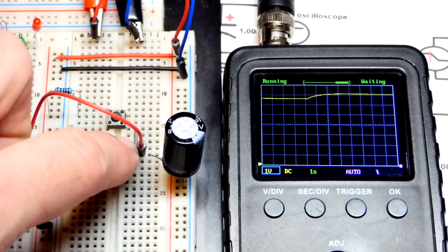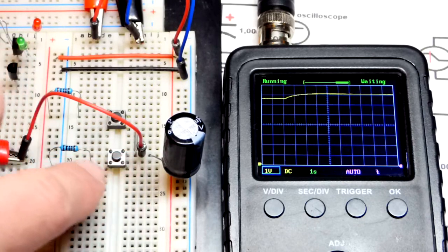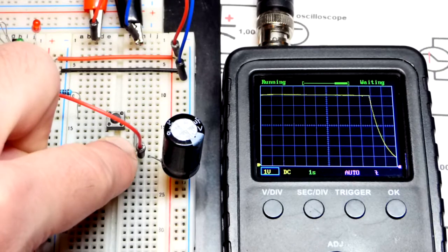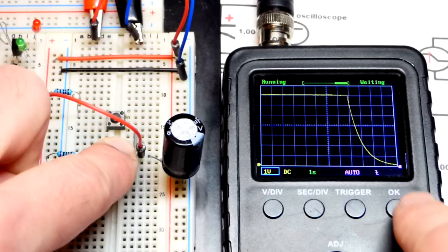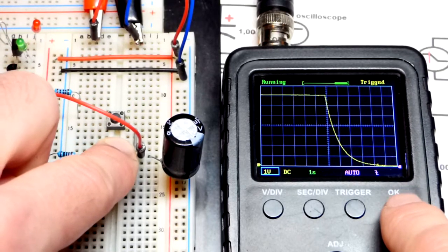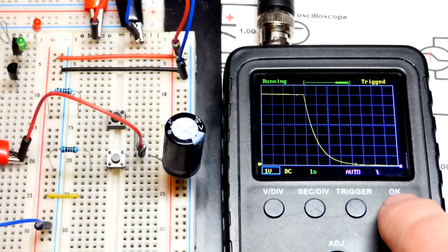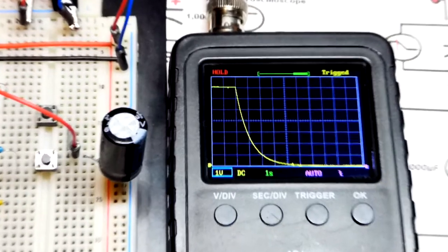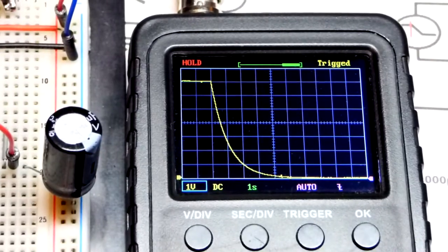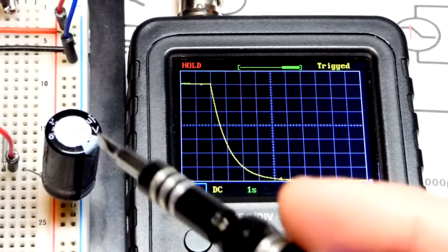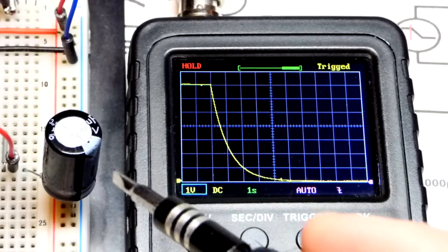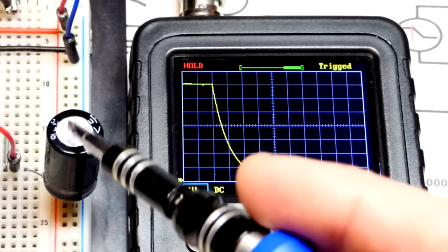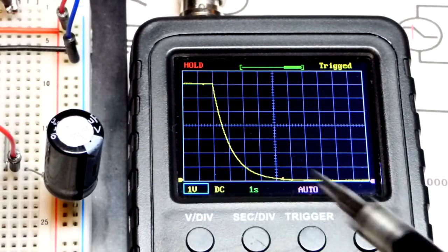Now we are going to hit this button and discharge it through a resistor. And there you can see we have the same curve, but in the opposite direction. And now I don't need to hold it anymore. I'll try to stop it right when it gets to a square, and I did pretty good right there. Again, same curve. We did the same process except we discharged it. So all the power that went through the resistor was provided by the capacitor.